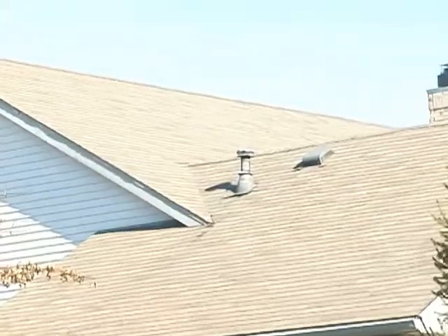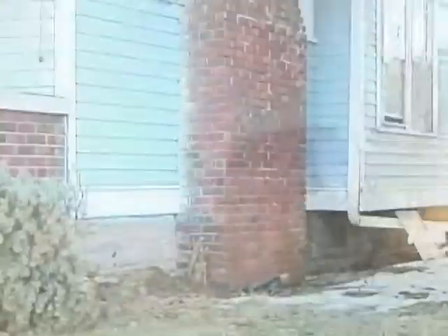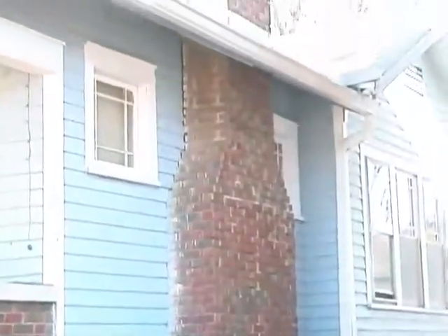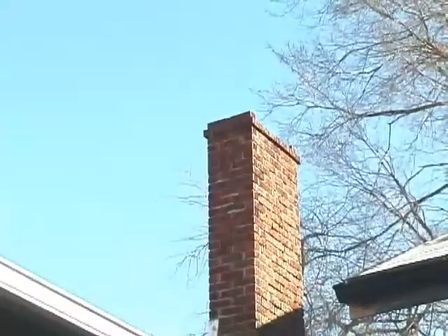An undersized vent may not be able to carry all the gases. An oversized vent can cause the gases to rise too slowly, losing heat to the chimney and thereby weakening draft. One of the worst venting situations occurs when a gas furnace that needs, say, a 5-inch diameter pipe is vented into a tile-lined 8-inch by 8-inch masonry chimney.